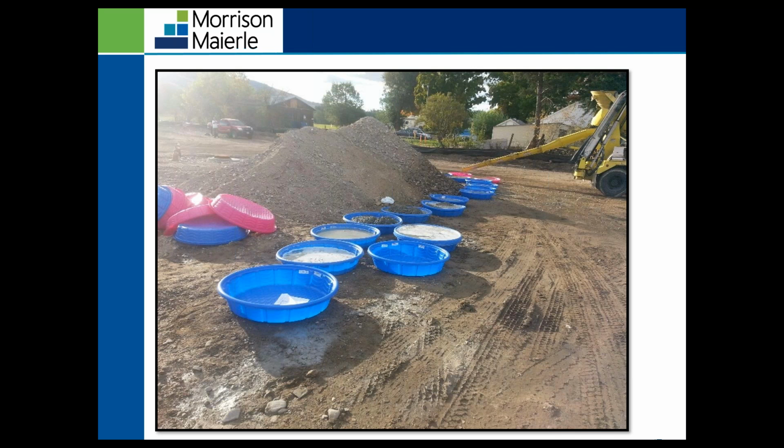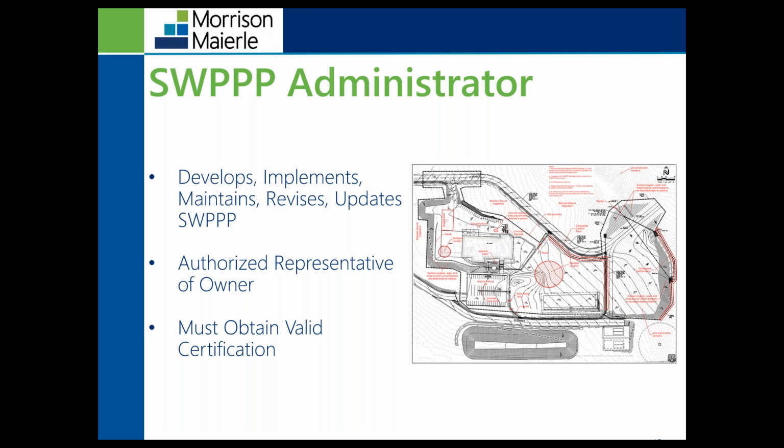So the SWPPP preparer is preparing, identifying, designing BMPs for your construction site, calling them out. Then once DEQ authorizes you to discharge stormwater from your site through a confirmation letter, then the SWPPP administrator takes over and performs inspections.